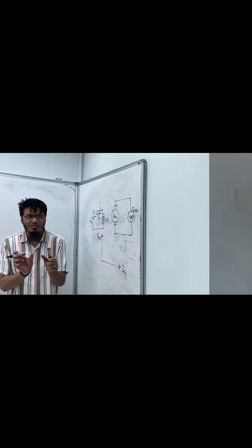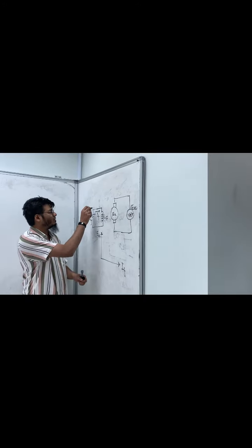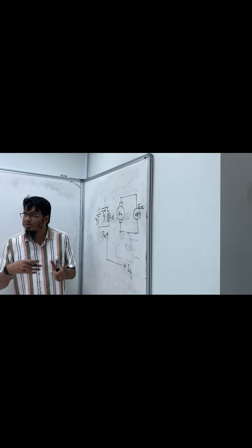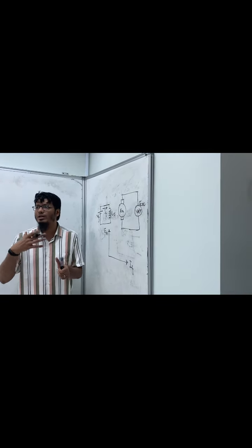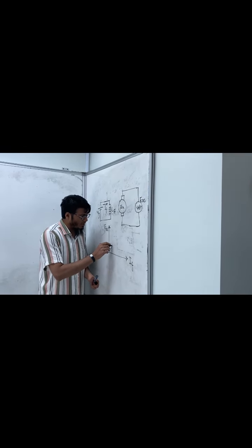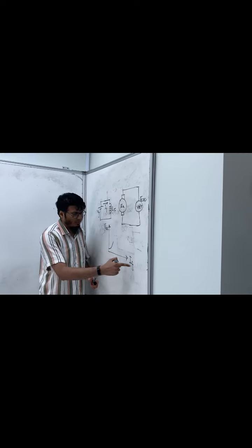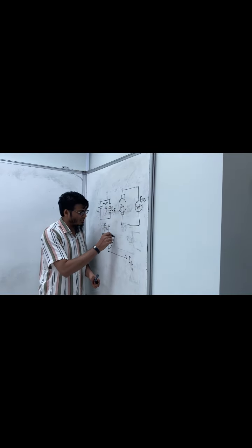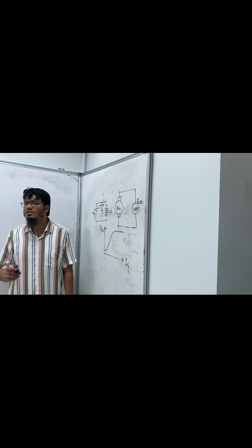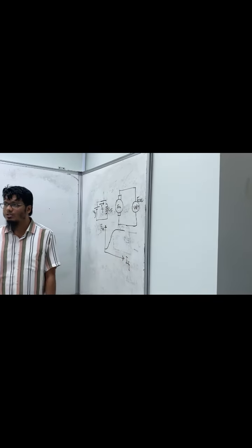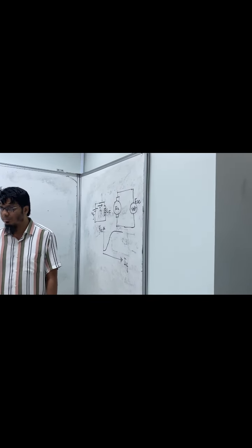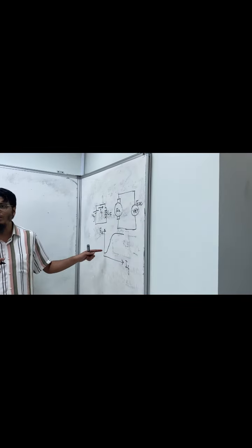But actually the relationship is that if you increase the field current, the field is getting stronger, and because of that the armature is getting more electrical energy, right? So that means we get a curve something like this. The more we increase the field, EA is getting increased, and then it reaches saturation. Are you with me? This is the same as the magnetization curve we plotted in chapter number 2, the B versus H characteristics curve. Remember the magnetization curve? This is looking similar, right?